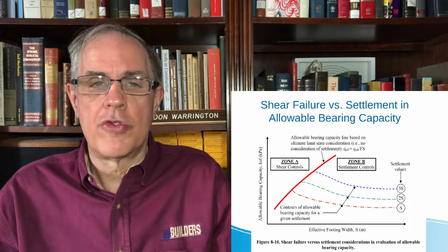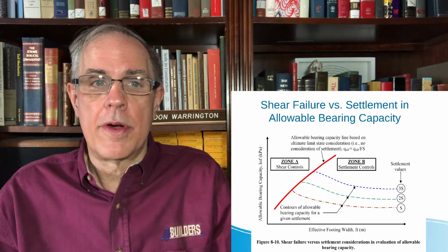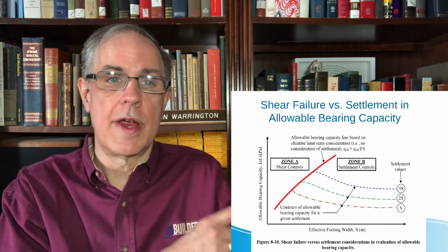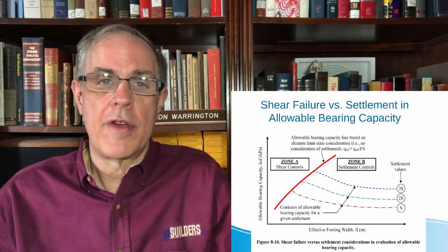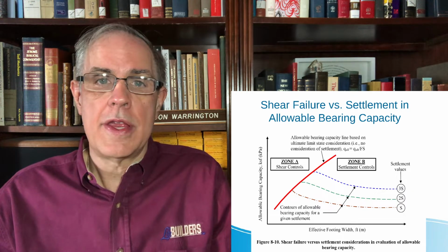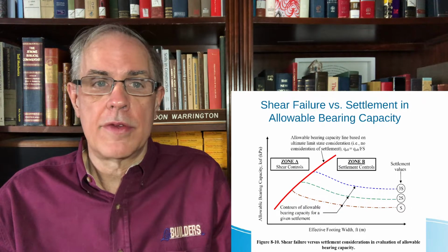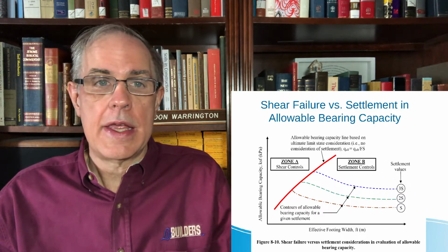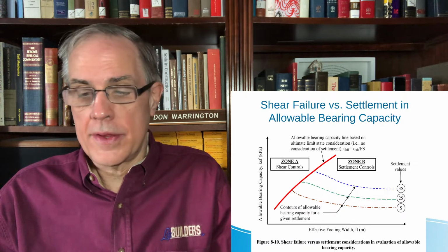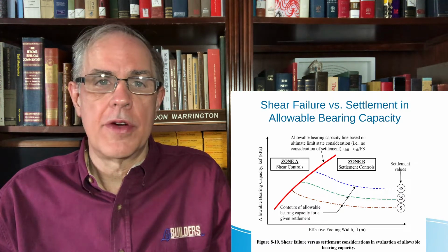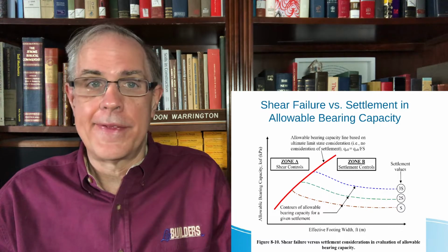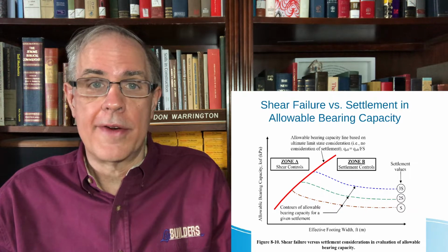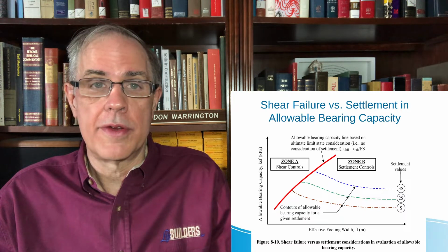It depends upon the soil. It depends upon the width of the foundation. For example, this diagram shows that the narrower your foundation is, the more bearing capacity dominates. Whereas if you get wider, then settlement tends to take over. And of course, that depends on a lot of other things. For example, how much settlement can your structure tolerate? That's an important consideration.